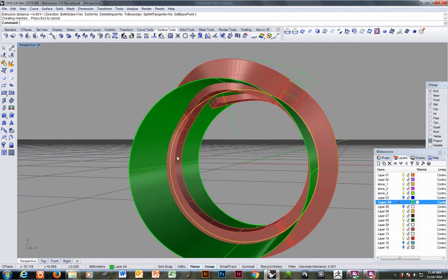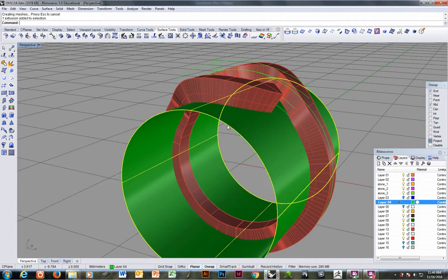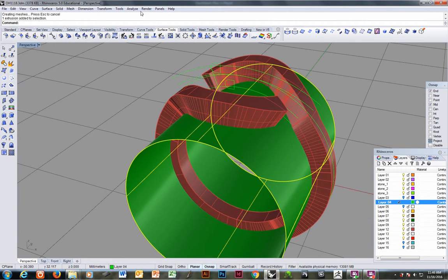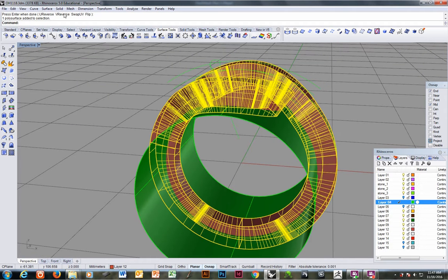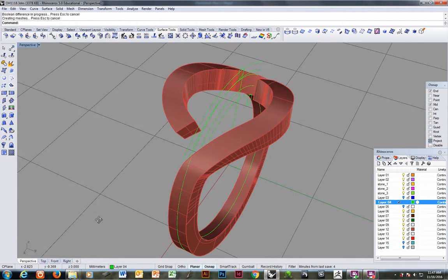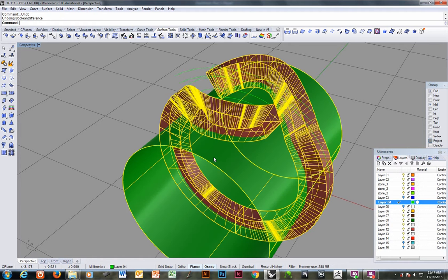There, see? I'll be cutting this bottom off eventually, and that will be how high your ring is. I can do that whenever I want to. All I've got to do is analyze the direction, make sure it's pointing outward, do a solid difference, and it's ready. I am not going to do that though, because I like overlapping. I like things too long. When I finish the ring, when I assemble it, then I'll clean it all up. But until I'm ready to assemble, that extra meat makes my life a little bit easier.